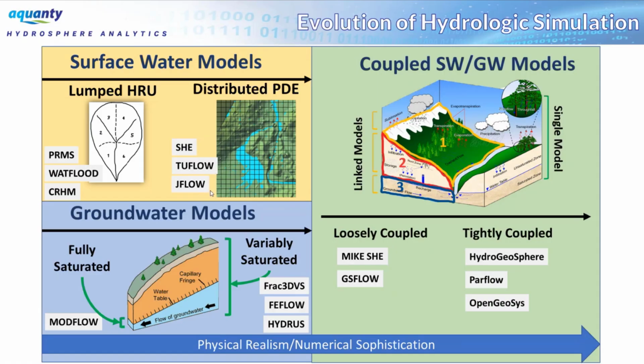Xi, 2-flow, J-flow are all examples of that. But really, you have a governing equation of flow, and that governing equation of flow is applied at every grid cell or node within that system of equations. This is primarily the way that groundwater models have worked. There are analytical groundwater models out there, but by far the most common groundwater model in the world is MODFLOW, or models based on the MODFLOW family of codes.